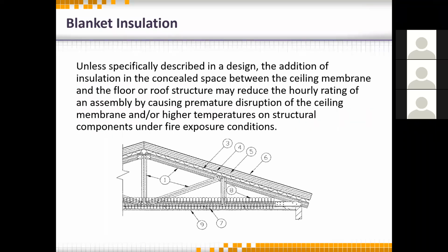So this is an interesting one too. We're showing here a ceiling roof type application, and the picture shows insulation there. Let's assume just for a minute that there's no insulation. We passed the test without it. You all specified it, and that was installed. Building's occupied. 3 months down the road, the local airport decides they're diverting the way the airplanes fly in and out, and it's now coming right over your building. What's the best way to get more soundproofing? Throw in some insulation up there.